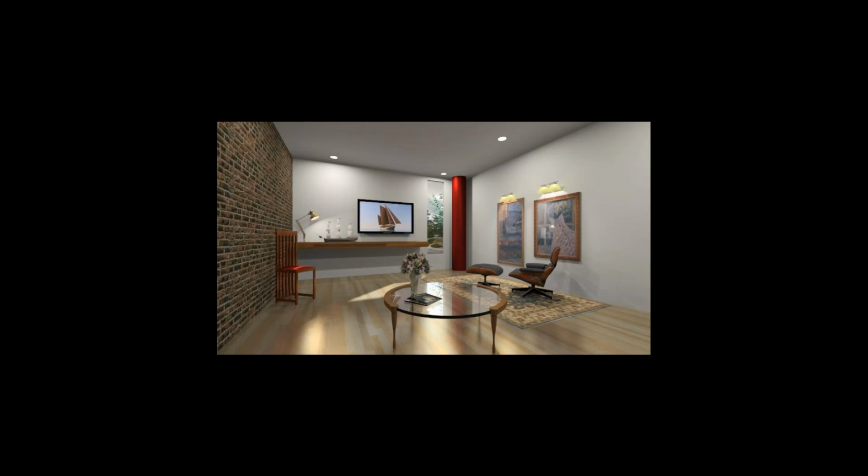Now when I complete the rendering, let's look at the differences. So the lamp now, instead of being a matte finish, is very glossy, very shiny. I'm getting nice reflections in the floor, and I'm getting very fuzzy reflections of the light, which is exactly what I was after. Kind of a nice satin finish on this floor, not quite so mirror-like. My vase renders beautifully. I've got a nice thick glass table. I'm getting good highlighting on my column. And if you remember, I put glass in front of my pictures.